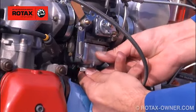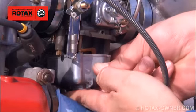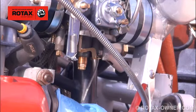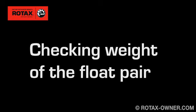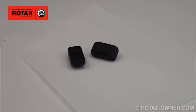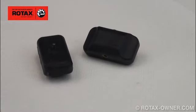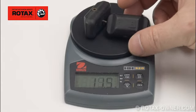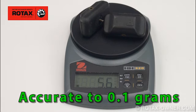The weight inspection will indicate if the affected floats have absorbed fuel. This check is not relevant for new spare parts which have not yet been in contact with fuel. Let the floats air dry for 1 to 2 minutes. Only weigh dry floats. Check the weight of each pair of affected floats using a calibrated scale. The resolution of the scale must be at most 0.1 grams.